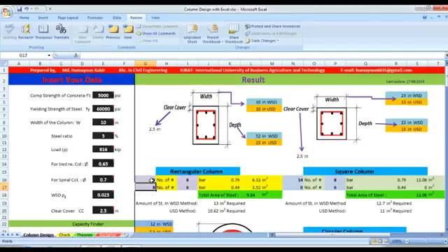So let's increase the number of 8 bar. Let's increase 2 bars, so 10 number of 8 bar. It comes to 11.42 inches square, which is bigger than the required steel. So let's keep it 8 number of 8 bar, and let's increase the reinforcement here, 10 number of 6 bar. So 10.72, which is slightly similar to the required steel, so we will use 10.72 inches square.